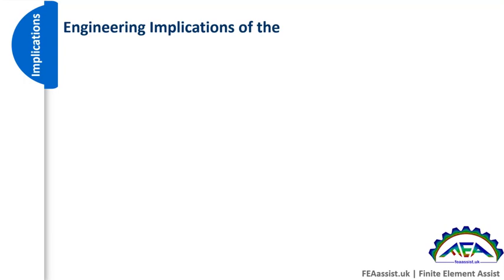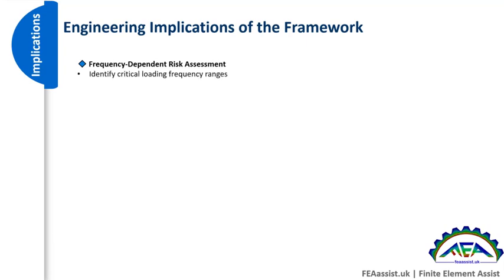Implications. Engineering implications of the framework. You can use it for frequency dependent risk assessment, identify critical loading frequency ranges, identify and predict safe and unsafe fatigue regimes, and evaluate service conditions under hydrogen environment.